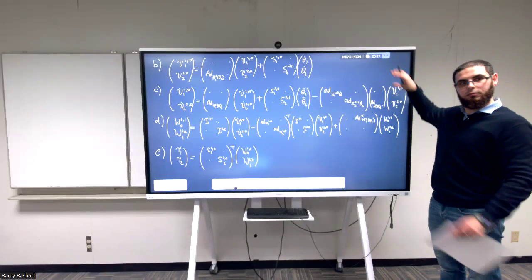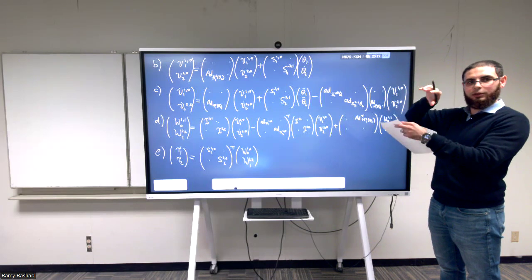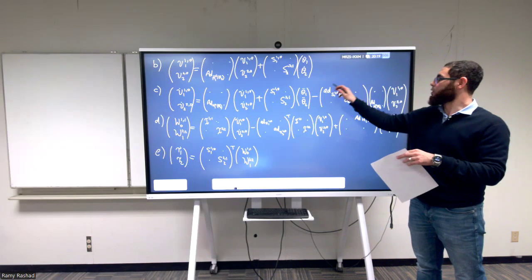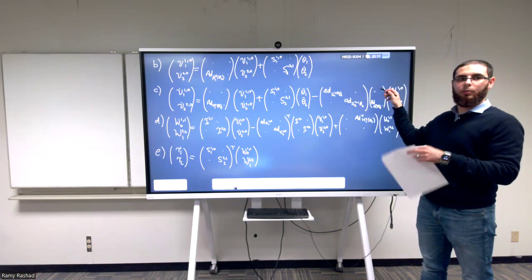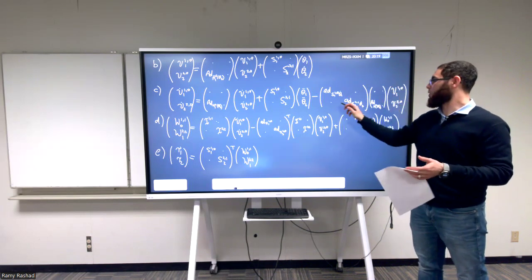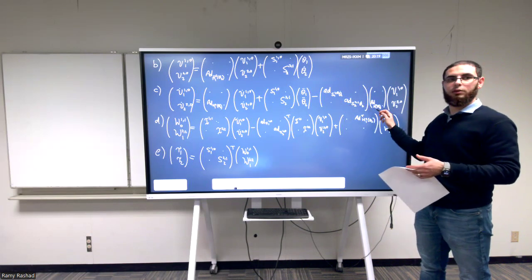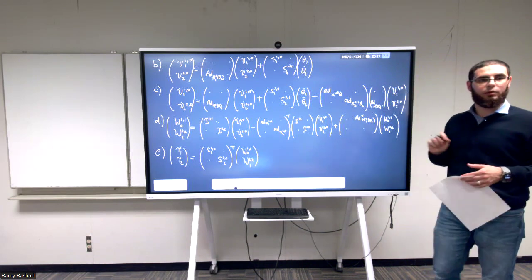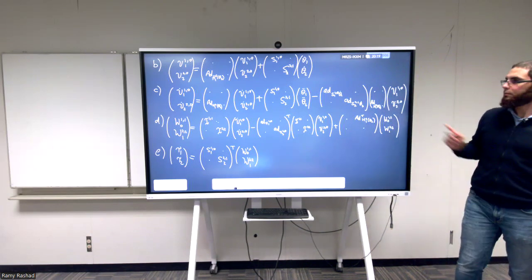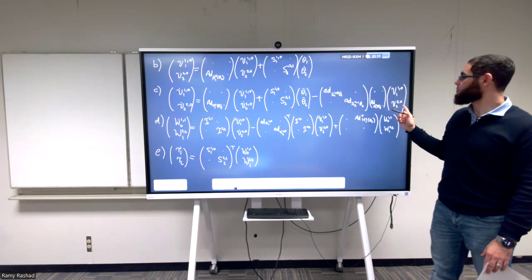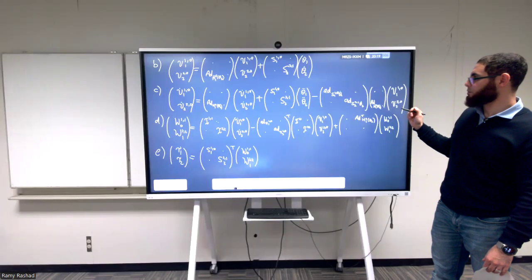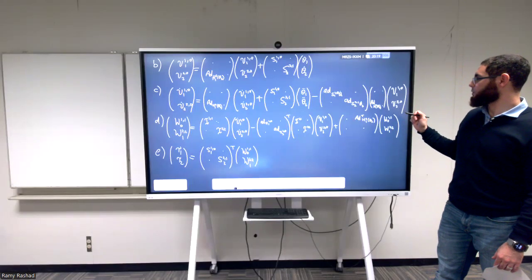And then take these two blocks, one on the top and one on the bottom, and multiply by this diagonal block matrix, right? So this one on the top, which is 0, gets 0. The one on the bottom, you get this one multiplied by the one on the bottom, which in the end you see, we recovered the small adjoint, big adjoint multiplied by v1. But here, we're expressing it in S and theta dot. But when we're writing the wrench equations, we're expressing it in terms of V. So is there a difference, or is it just a choice? No, that's just a choice.